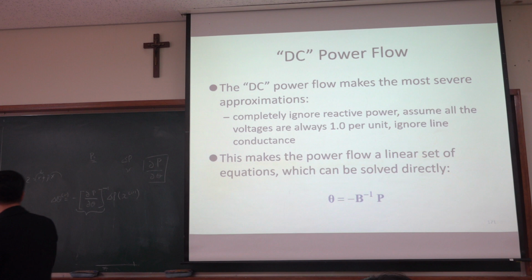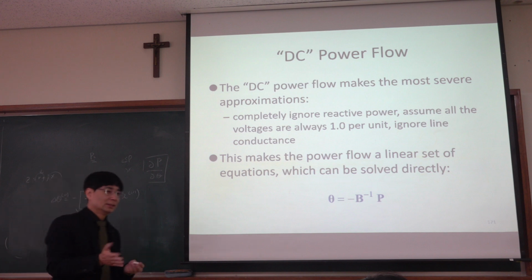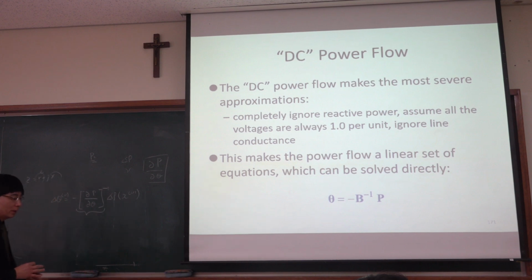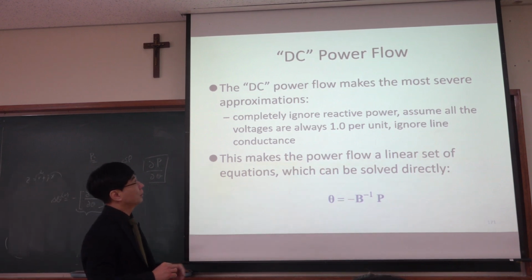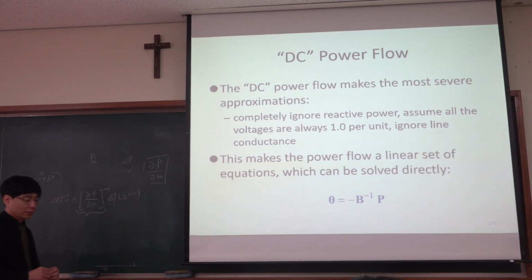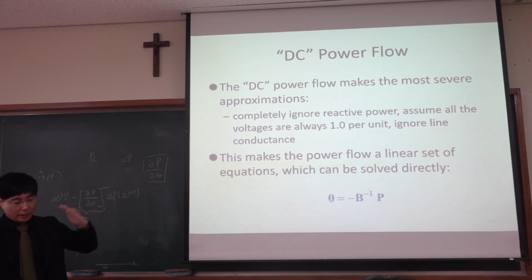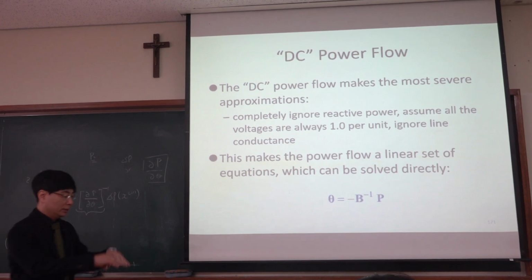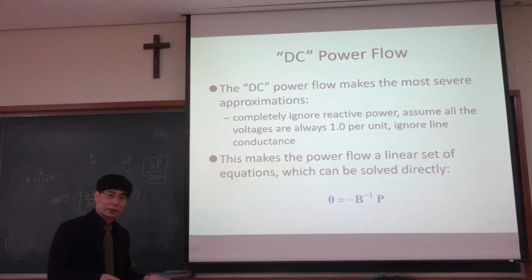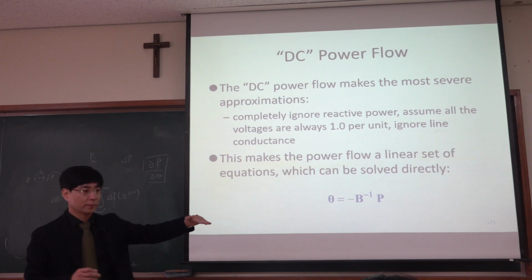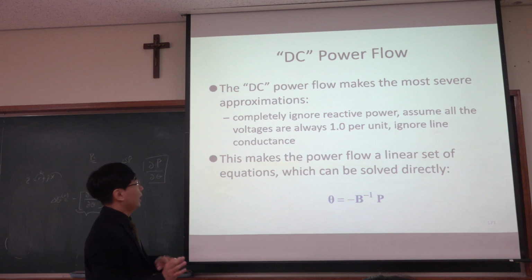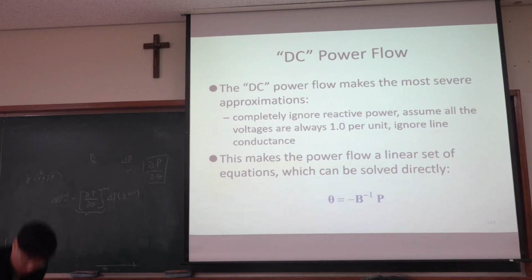And the reason why we are using DC power flow is because of what? We ignore reactive power. We only focus on active power. Because we ignore reactive power, the naming is DC power flow. I don't like that naming because that assumes our power system is AC power systems. That was true, but now we have DC distribution networks, DC microgrids, high voltage DC connections. In that case, they also have power flow, right? So the naming is confusing. Anyway, here, this power flow assumes AC power systems.